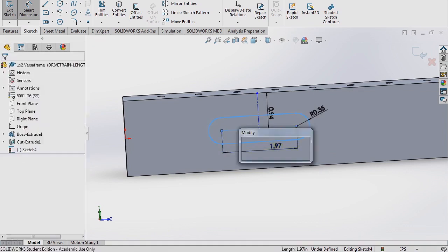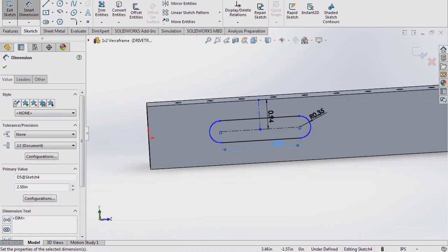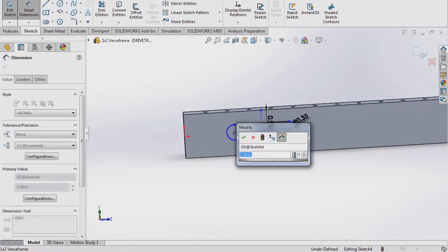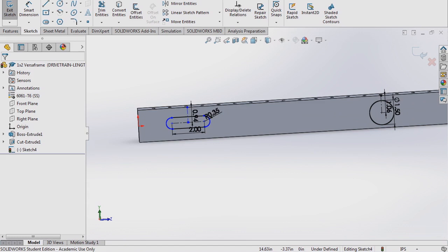This is just the amount of sliding room you're giving your shaft. Let's make it 2.5 inches. Or maybe just 2 inches. It's fine. So typically at this point you want to think, what do I need to make the center to center distance of my sprockets with my length of chain that I need? In the drivetrain, you don't really need to be thinking about this, because you can slide your sprockets to make the chain nice and tight. But in your mechanisms, you do need to be thinking about this if you don't have slots.